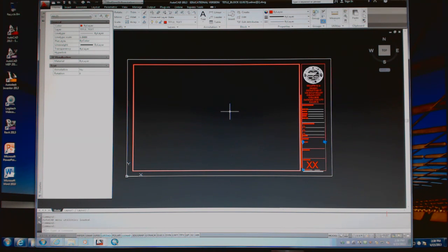All right, so any questions? Go by the book on a lot of the layer names, but then try to use my line types as a guide for how you need to do it. Because in there it shows the walls are a little bit thicker than a lot of the symbols and stuff like that. So use the walls as 0.5, symbols as 0.3, kind of things like that. Because I'm testing you on your presentation skills on this. It's basically presentation and setting everything up and all that kind of stuff. All right, no other questions? I'll free your computer and you can go.